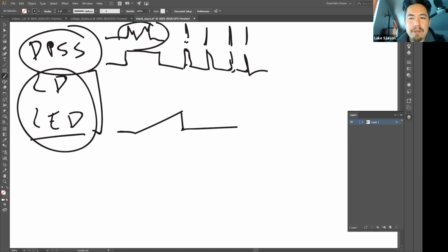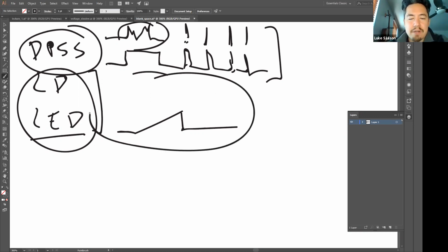That's an example of something where you might use digital control and pulse width modulation versus analog controls, where you're controlling a current driver that has a feedback loop that passes current through either of those two.